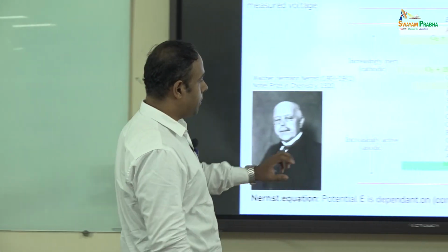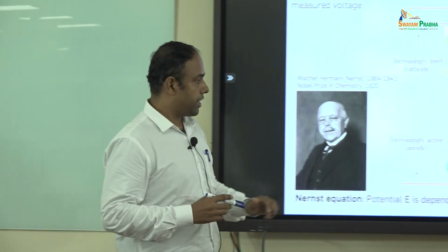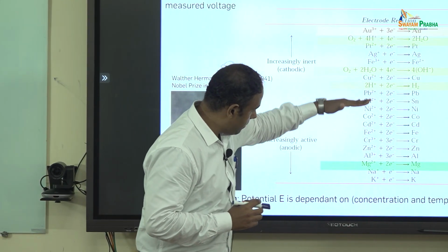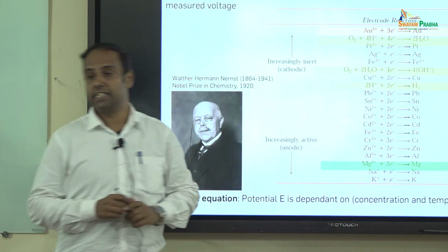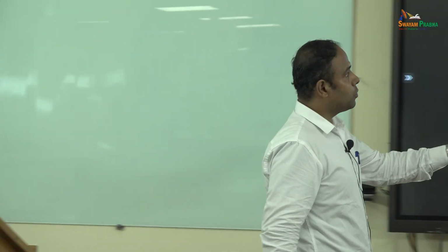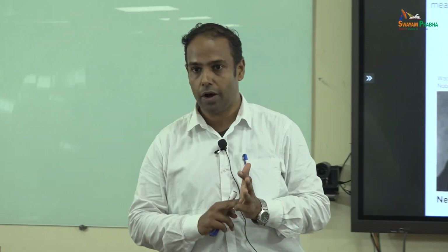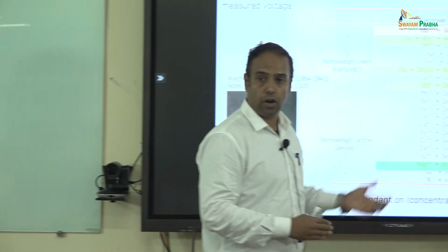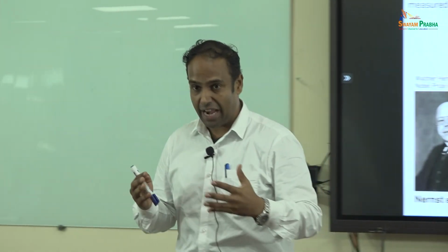Now, if I consider magnesium and zinc, what can you understand from here? Can I have magnesium as an anode for zinc? So, in this table, if you are below, that means you are increasingly active. If you are above, you are increasingly nobler. Now, the question is, what am I going to do with this? It is all elements. I have no alloys in the structure here. I don't talk about stainless steel. I am not talking about aluminum alloy, nor nickel alloy or copper alloy systems. These give relative placements of elements alone.